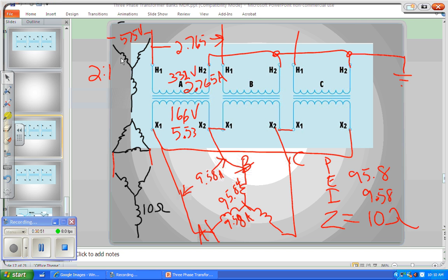Because then, our book, by the way, does talk about how to calculate the loads when it's a center tap delta, because all we do is we have more single phase load on one of the transformers, right? So one of the transformers is going to have to deliver more power. That's all there is to it. So that's pretty simple.